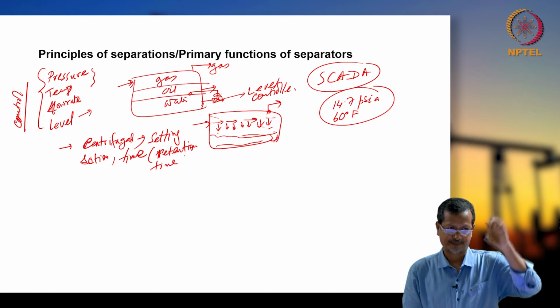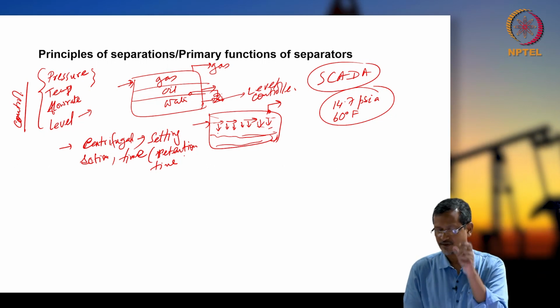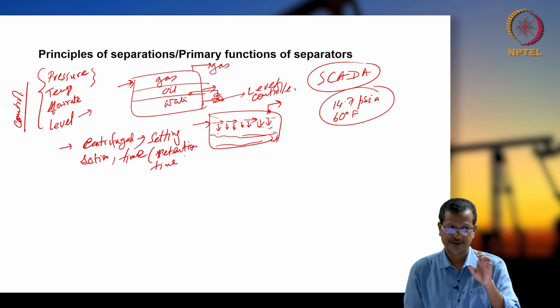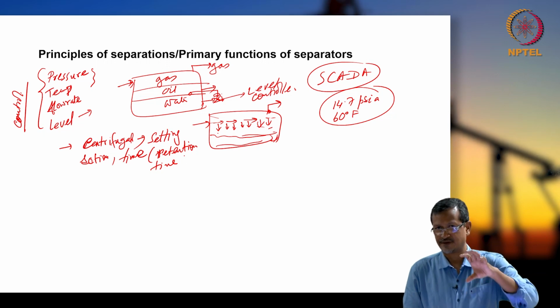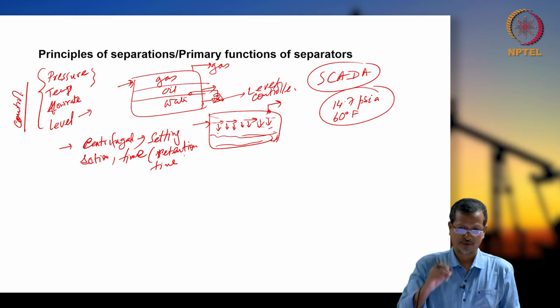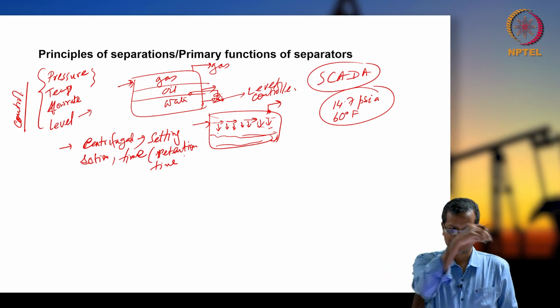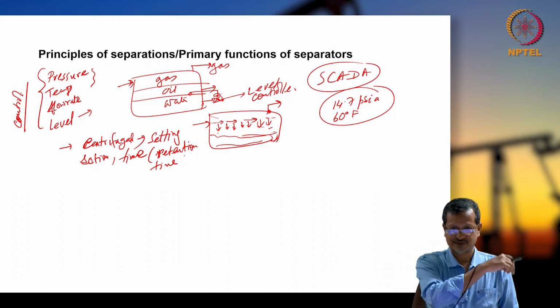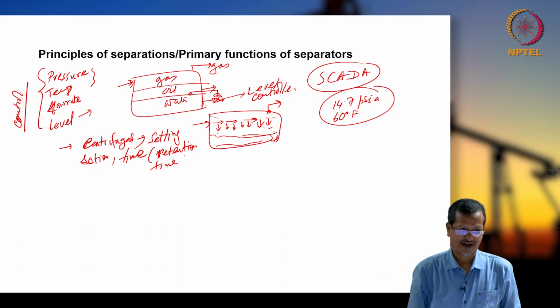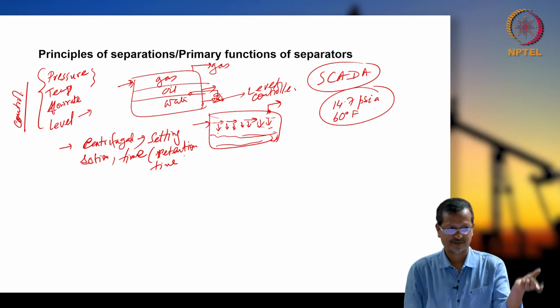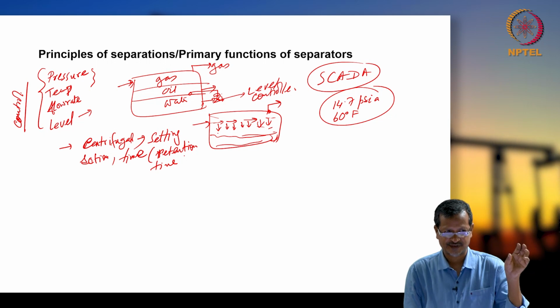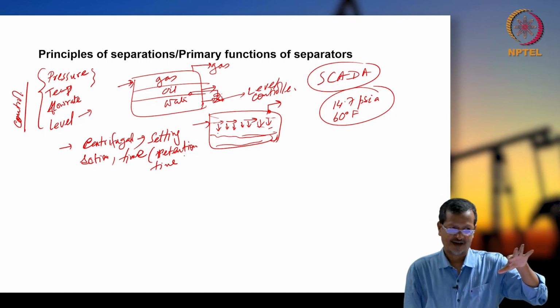There will be vertical separators, horizontal separators, cyclones, hydrocyclones, then scrubbers, then contactor columns. Everything will be working in a synchronized way. If your reservoir pressure is going down, that means the whole separator system may not work. Then how do you handle that? You may have to put in an extra compressor to give the pressure, so the whole system will be untouched.